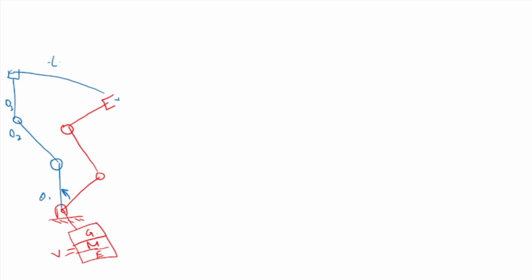As we go along, we'll talk about forward kinematics and inverse kinematics, which give the relation between the end effector position and orientation with respect to the joint angles. This basically means that we need to know how much every joint has to move to take the end effector from some point to some other point. Now, how do I know the position and orientation of the end effector with respect to the base frame?